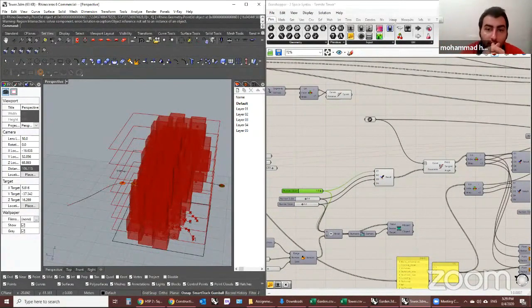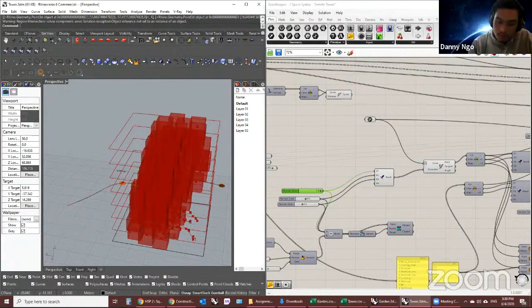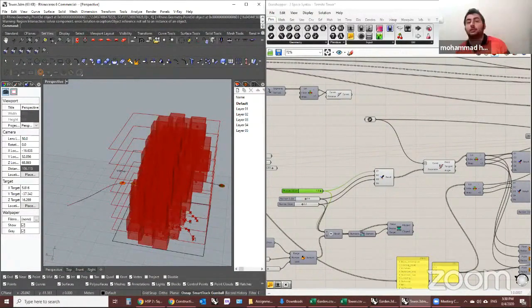In the first steps, we just generated the geometries, and then we implemented a recursive process that takes the geometries, plans them, and records them as an output. Then we have a tree with a lot of geometry with different space plans in them. We sort them, find the best ones, select the desired shapes, and then start calculating the energy efficiency for them.